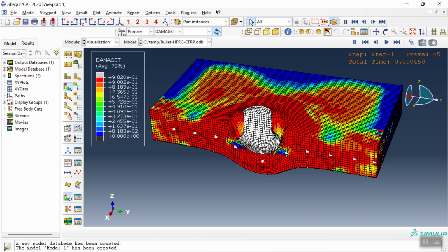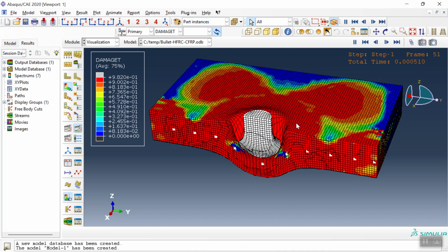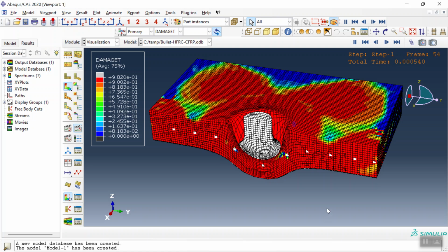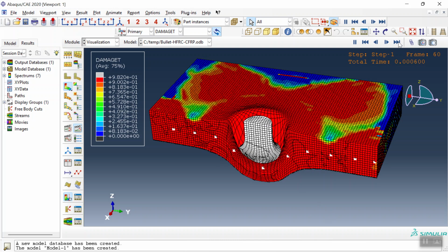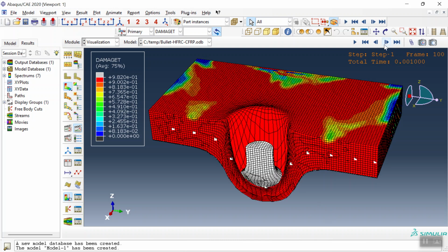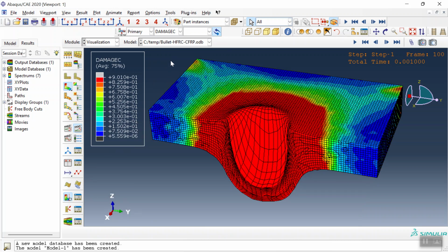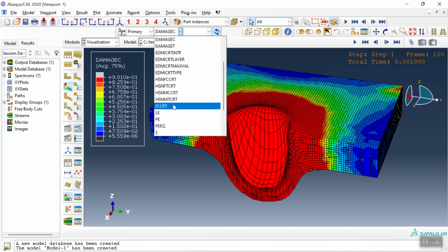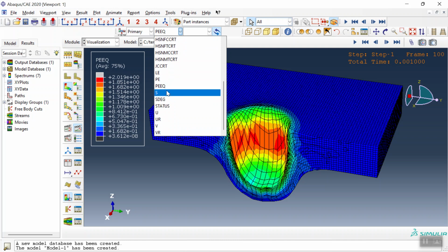This is the penetration and the deformation of the bullet. See, it is a strong panel and it has good resistance, but overall it failed under 500 meters per second velocity. So let me replace this, just the steel polypropylene hybrid concrete panel. This is a full view, this is the half view, compressive damage, plastic strain. See, it is too much, it means it is fully failed.